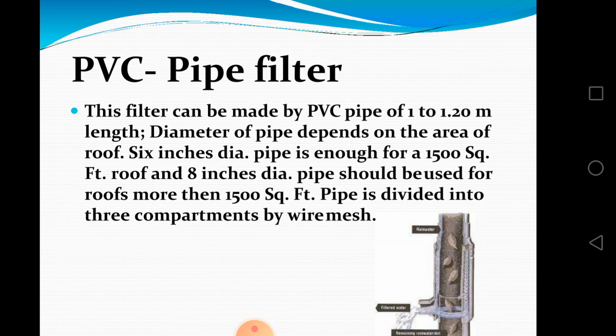Collection efficiency accounts for the fact that not all rainwater falling over an area can be effectively harvested because of evaporation, spillage, etc. That way we have to account for a factor called the runoff coefficient. Generally, in most rainwater harvesting designs, we take the runoff coefficient. Then we can utilize this coefficient to identify how much the water harvesting potential is for that particular area. This is a small description related to that.